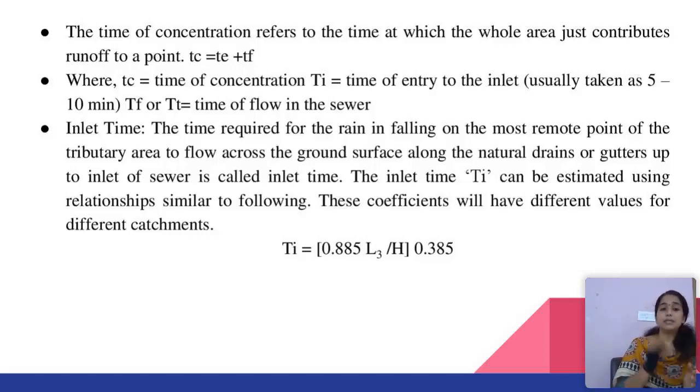The inlet time is the time required for the rain falling on the most remote point of the tributary area to flow across the ground surface along the natural drains or gutters up to the inlet of the sewer. The inlet time TI can be estimated using a relationship similar to the following.